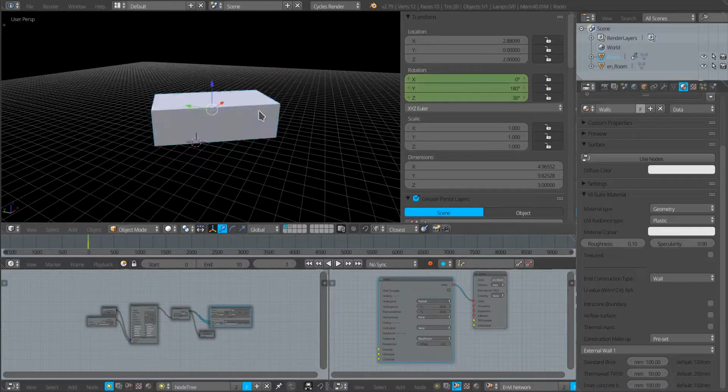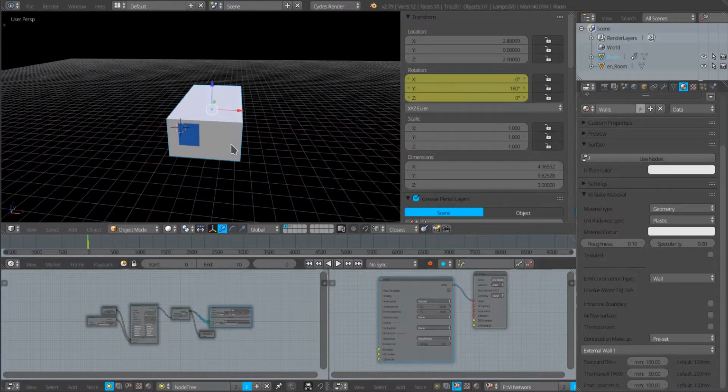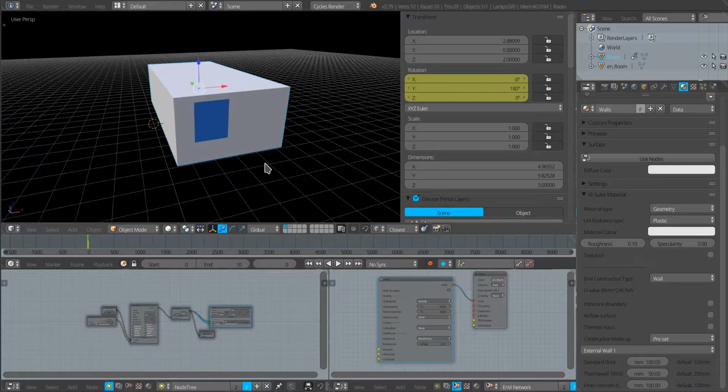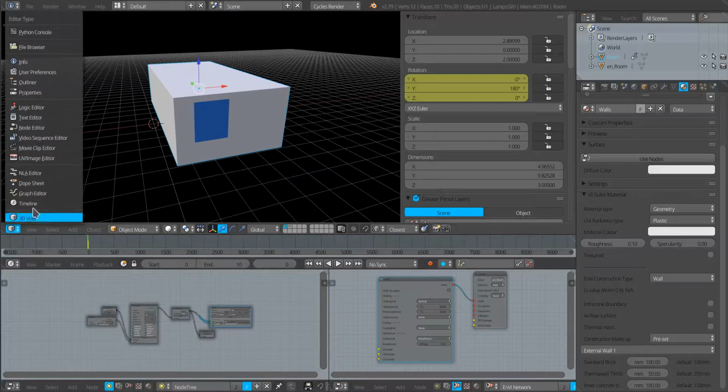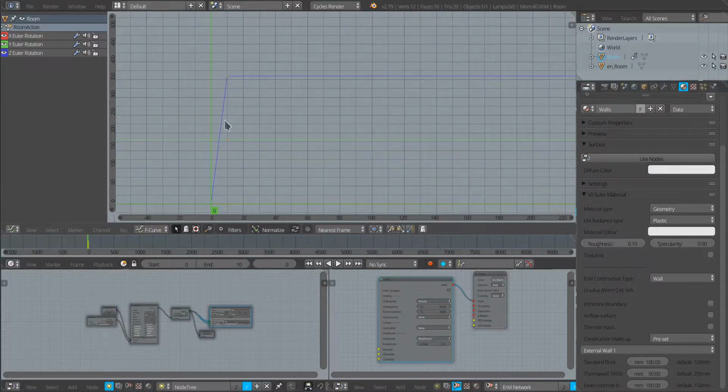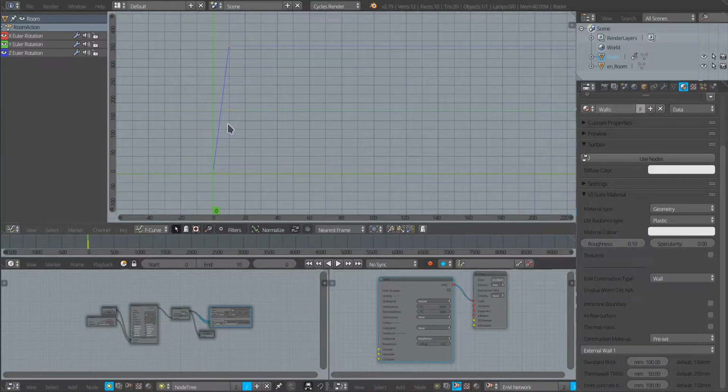So once that has become set up, we can now go ahead and proceed with the parametric simulation. Now I will just mention, while I think about it, if we come into the graph editor window, we can see that animation change, 0 at frame 0 to 360 at frame 10. And we'll notice that this is a straight line, which means every time I change one frame, an equal degree rotation will be enacted. This isn't, however, how Blender is initially set up.